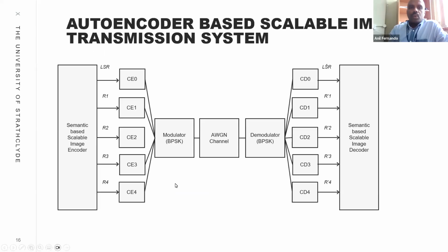On top of that, we have also used unequal error protection and equal error protection to protect this data at different levels. Being the most important layer, the base layer is protected more than the enhancement layers. Subsequently, the protection for enhancement layer 1 is higher than for 2, 3 and 4, and 2 is higher than 3 and 4. As we go from top to bottom, we lower the protection level, because there's no point in decoding R4 if we can't decode R1. That is the main reason for decreasing the channel protection for the enhancement layers from top to bottom.